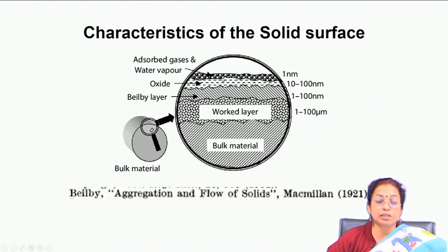If you talk about metallic materials which are highly reactive in nature, naturally there is the phenomenon of chemical adsorption, so chemisorption. So, near the surface there is always some oxide or compound layer formation, and below that compound layer again you will find a very thin amorphous layer which does not have any structure actually. It is called the Beilby layer because this particular structural feature is vanished on the surface because of some cold working operation which the surface has undergone prior to its processing actually.